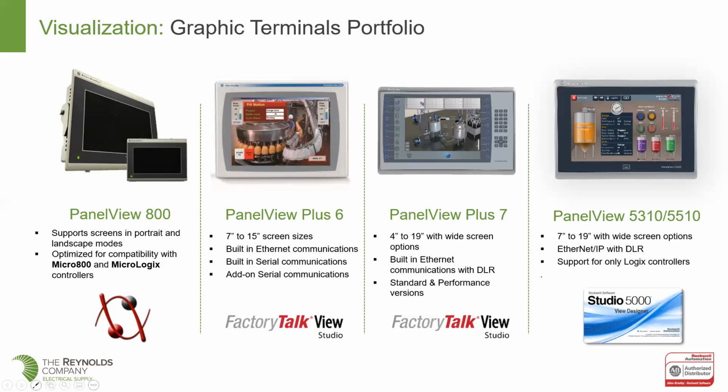The other unique thing, and again, we'll show more on each of these as we go, is that the 5000 family uses Studio 5000 software to develop the application. So if you bought Studio 5000 to do your Compact and ControlLogix applications, starting with, was it version 24 or 27 that View Designer came in? Mike, I don't know if you know that off the top of your head. I believe it was 24. 24. So starting with version 24, View Designer came along with Studio 5000.